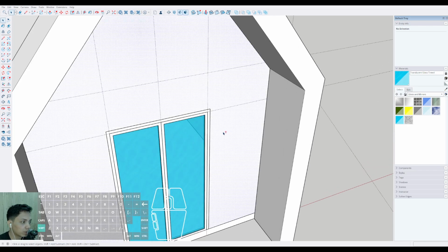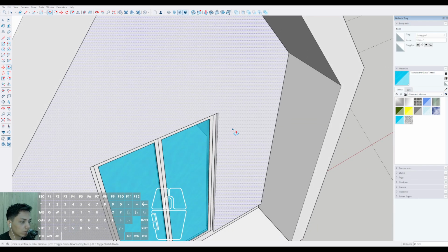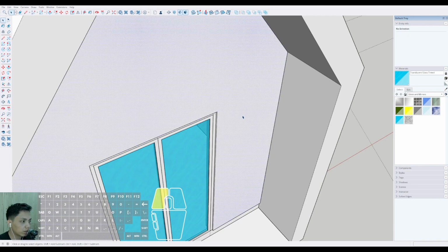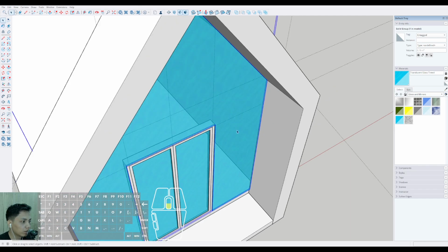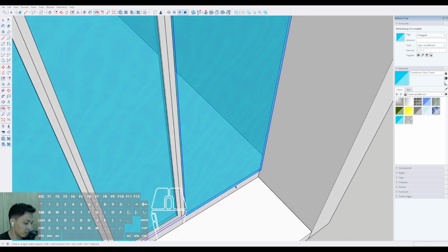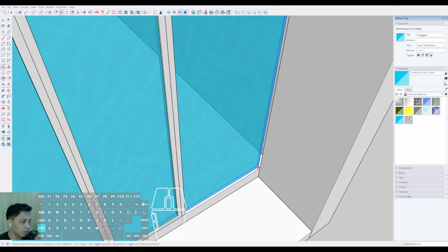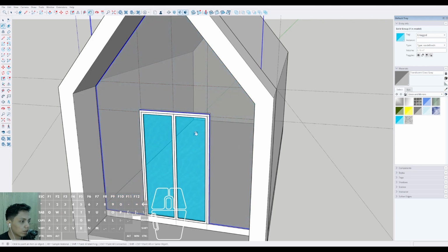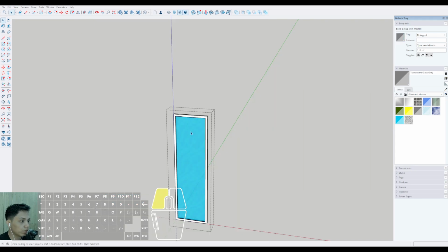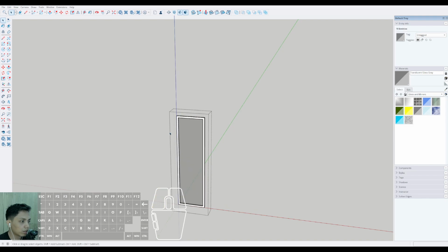Okay, so we can click this plane and push it to the front around 20 millimeters, triple click, right click, and make group. Then we can apply the same glass material, select move, place it in this position, and we can also adjust with another glass, for example.